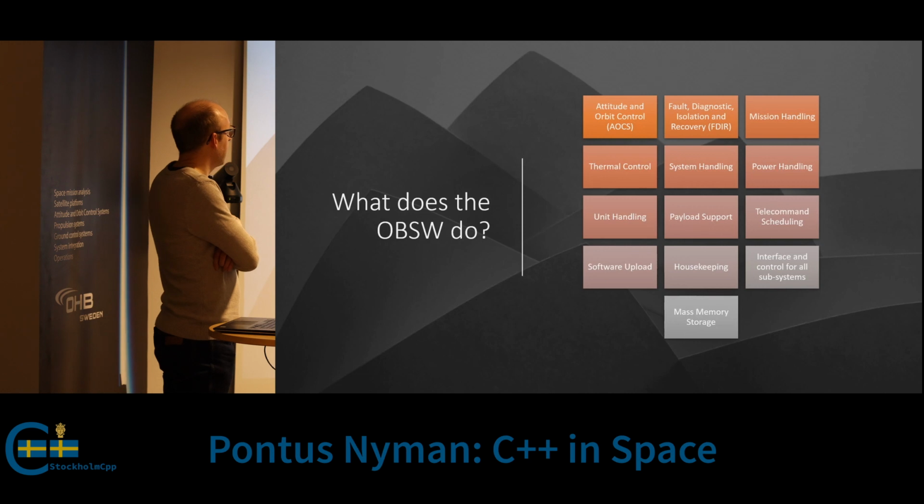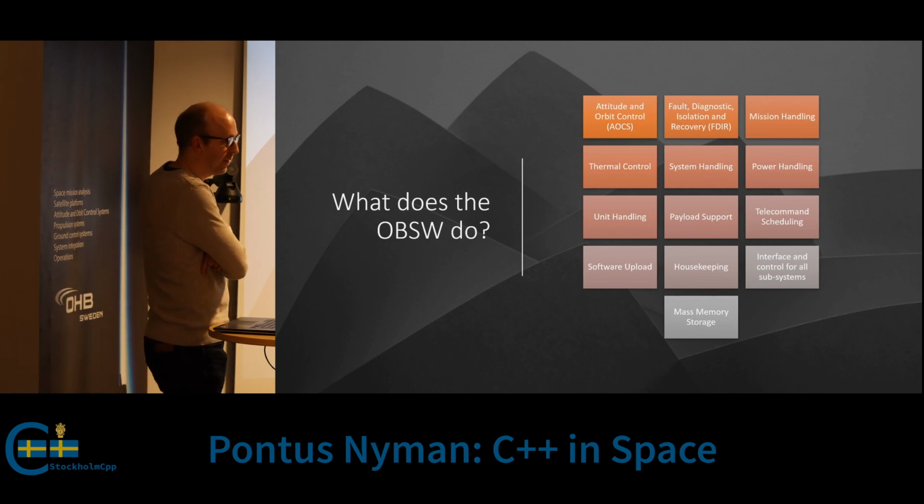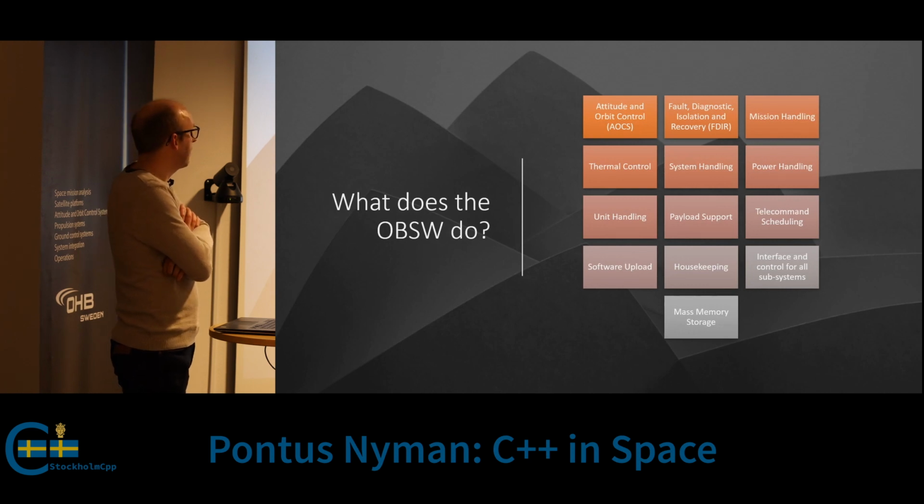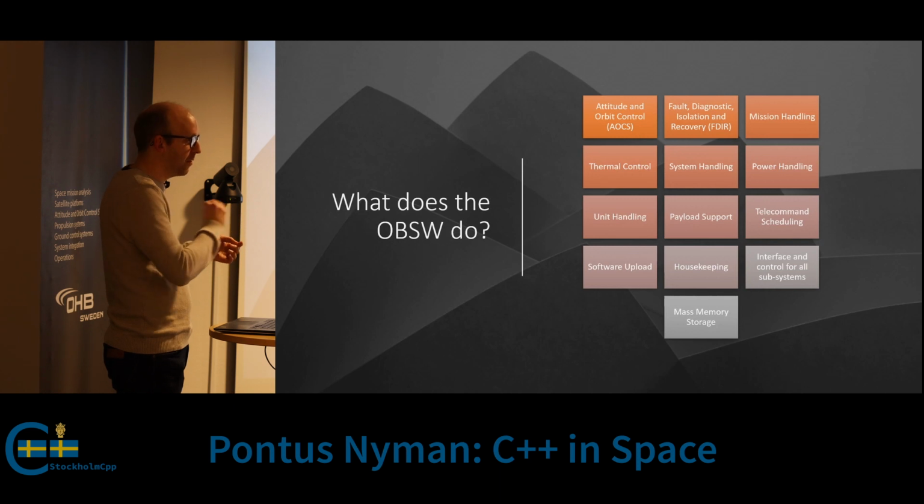Then we have something called FDIR, Fault Diagnostic Isolation and Recovery, and that's the part of software that's constantly monitoring everything and trying to find if there is something strange. And if it finds it, if it diagnoses it, then it isolates it, and then it tries to do various recoveries.